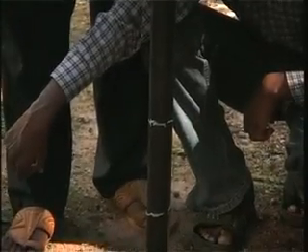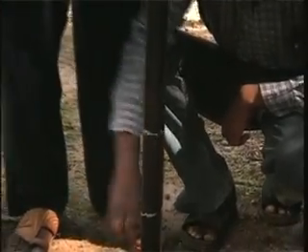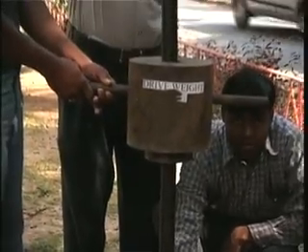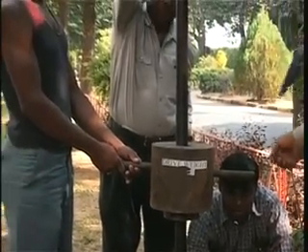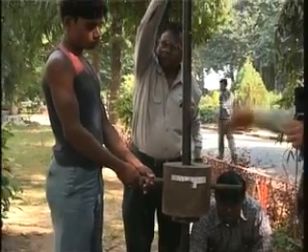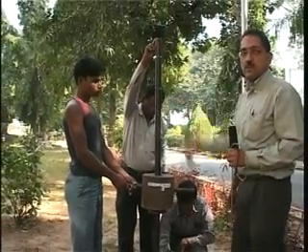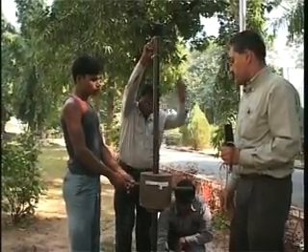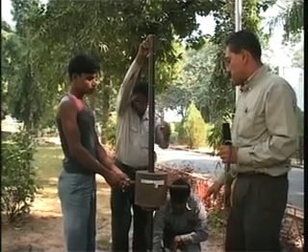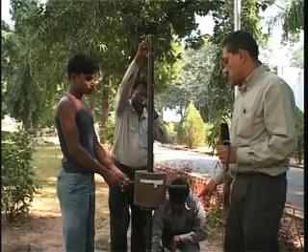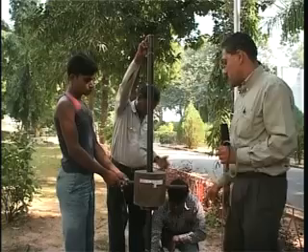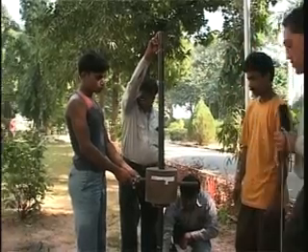So now you just be with us, and we are going to take help from two of my colleagues who are going to lift the hammer up to the 750 millimeter markings, which is also marked on the rod, and they are going to drop it on the anvil, and that is going to drive the sampler into the ground, and we are going to count the blows, as you are going to see in the next little bit.